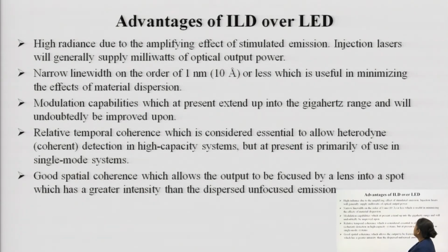Now, advantage of ILD over LED. The high radiance due to the amplifying effect of the stimulated emission: injection laser will generally supply milliwatts of optical output power. We already know that optical powers which are generated are of very low intensity, but in the case of injection laser, since stimulated emission occurs, the optical power gets improved.